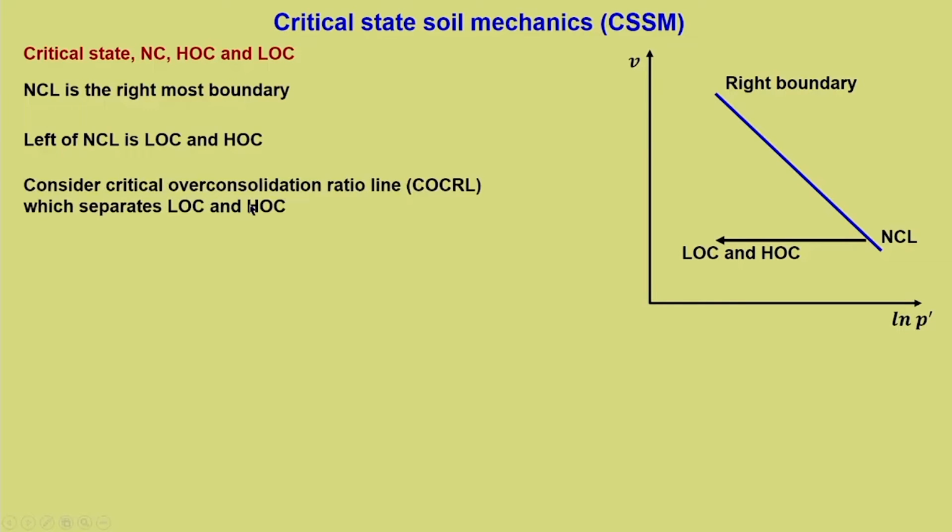Consider the critical over consolidation ratio line which separates lightly over consolidated and heavily over consolidated. We have already seen in module 2 that the behavior of heavily over consolidated soil is fairly different from that of the normally consolidated response. Understanding this response is very important to understand the critical state framework as well.